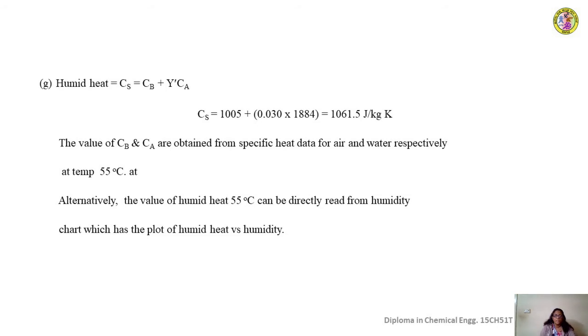In the present humidity chart that we are using, the humid heat versus humidity plot is not visible. So here we can't use that method. We have to calculate it theoretically using the equation Cs is equal to Cv plus y dash Ca.